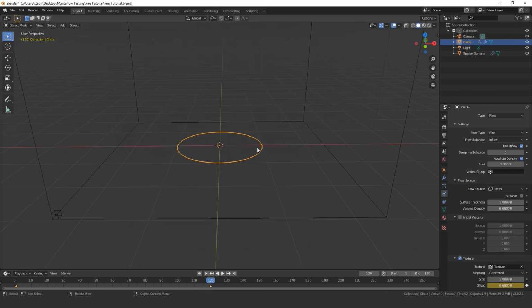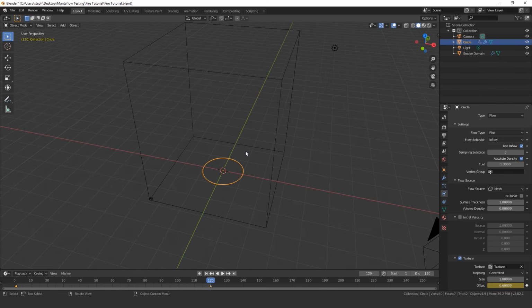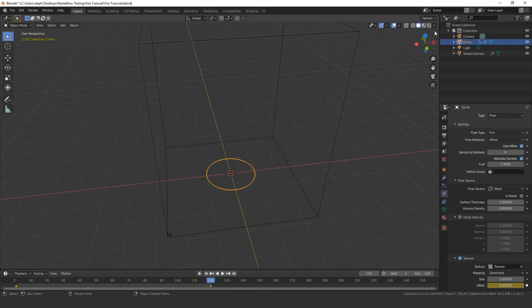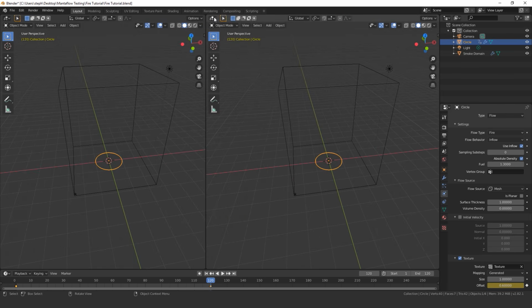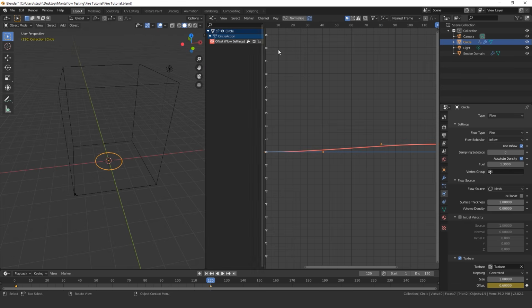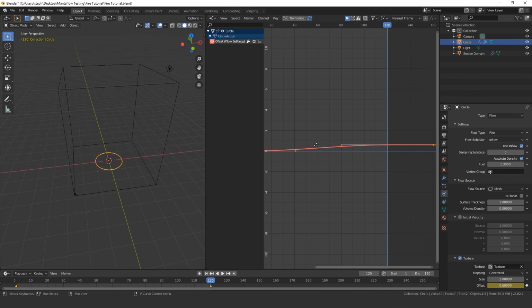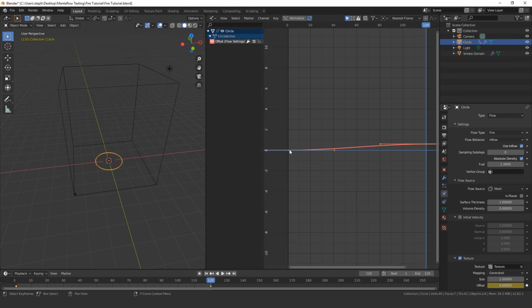When working with animations in Blender, it uses a curve to smooth out the animation, and this does not look very good for our simulation. So what we're going to do is open up the graph editor, so split the window, click on the menu, and go to the graph editor. This is what our current animation looks like. So it's basically starting out really slow and then speeding up in the middle here and slowing down at the end. We don't want this, we want it to be a linear transition, so press T and click on linear. And this will make everything a straight line.